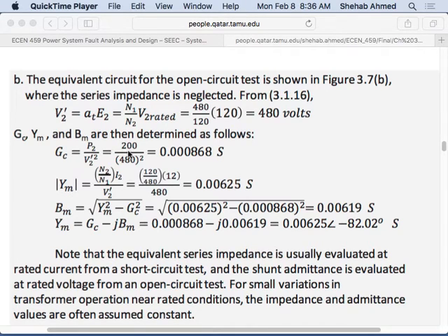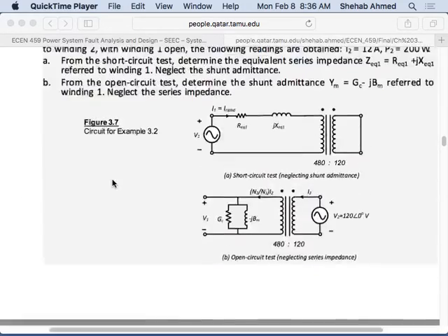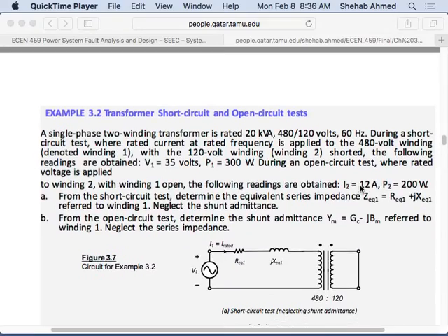Yeah, so the conductance was only a portion of that power, the portion of that impedance that is consuming that real power. Now, if I take my voltage and current, remember, I have excitation current as well. I think they told us how much current is flowing. Yes, they told us 12 amps is flowing, and 200 watts has been dissipated.